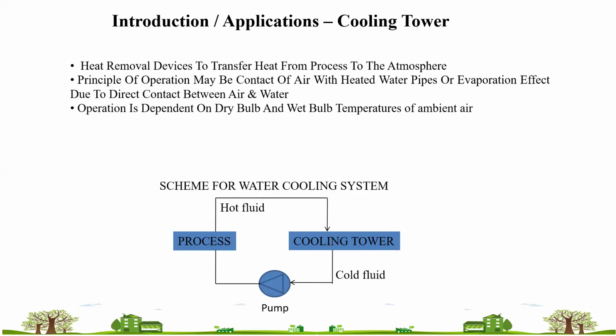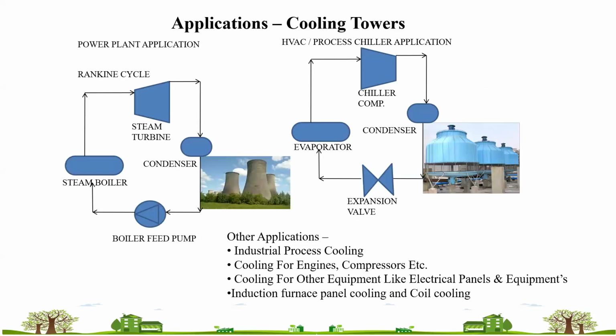So their performances, irrespective of the same configuration, may vary according to ambient air, because the cooling tower is directly connected to the chiller condenser, and the chiller condenser is a major deciding factor in the performance of the chiller. That's how ambient air plays its role.